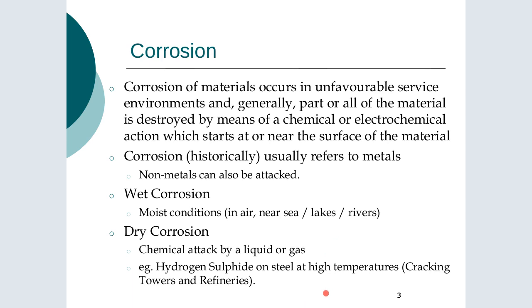Similar in places worldwide, China will have particular regions where they have a high concentration of the process industry. And what you may find is that your environmental conditions may change arising from the atmospheric quality due to emissions of plants there. So when you're designing, you may want to look at the pipeline of what is planned for the process industry in that region, and what are the expectations regarding, for example, air quality, because that may change your environment and change your rate of attack as well.